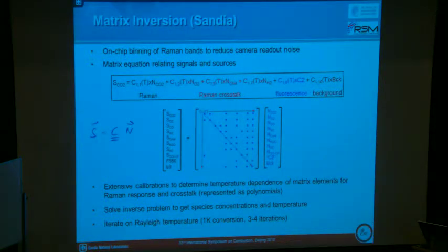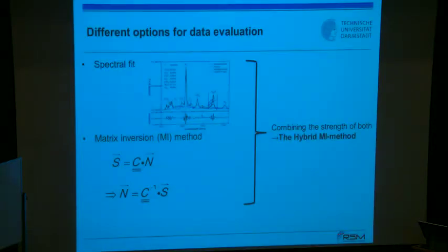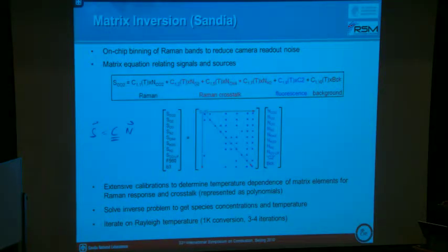In an ideal world, if everything would be separated spectrally, you would have matrix elements only on the diagonal. But you see off-diagonal elements as well. I go back to this view graph over here. The problem is, let's take an example, CO2 and O2. They spectrally overlap. We call that a crosstalk or an interference. So if you have a certain limit where you integrate all your CO2 information, O2 information shoots in, and vice versa. The same holds true for N2 and CO and so on. And that's why you find matrix elements at those locations where you have these crosstalks.